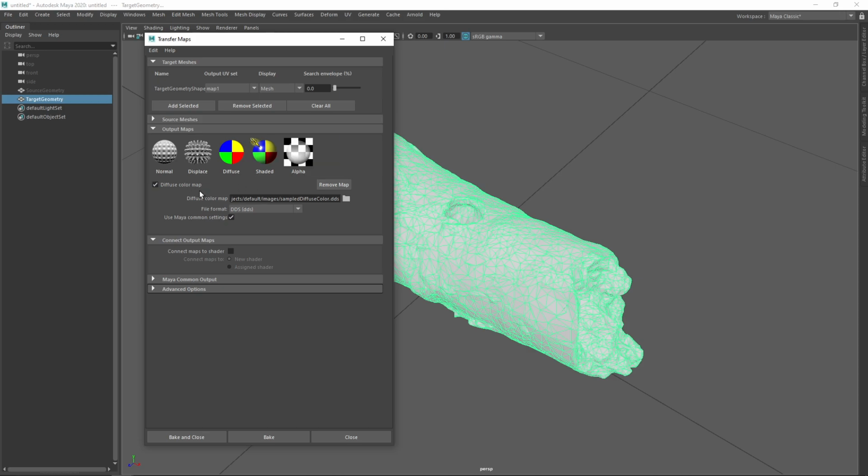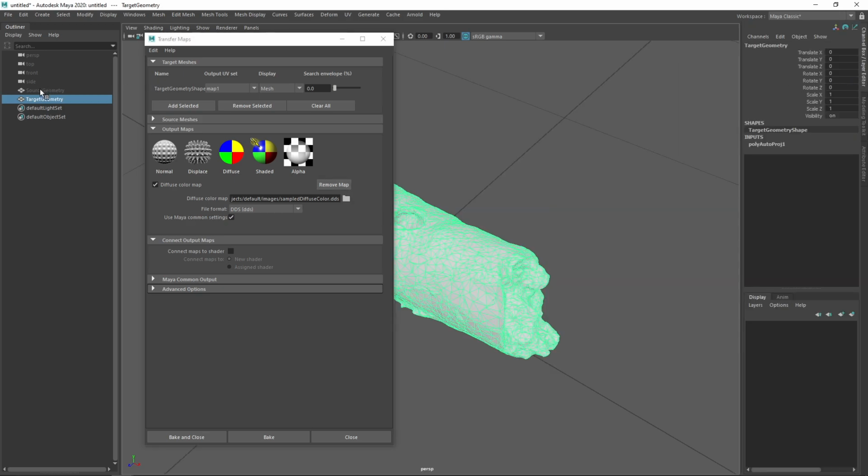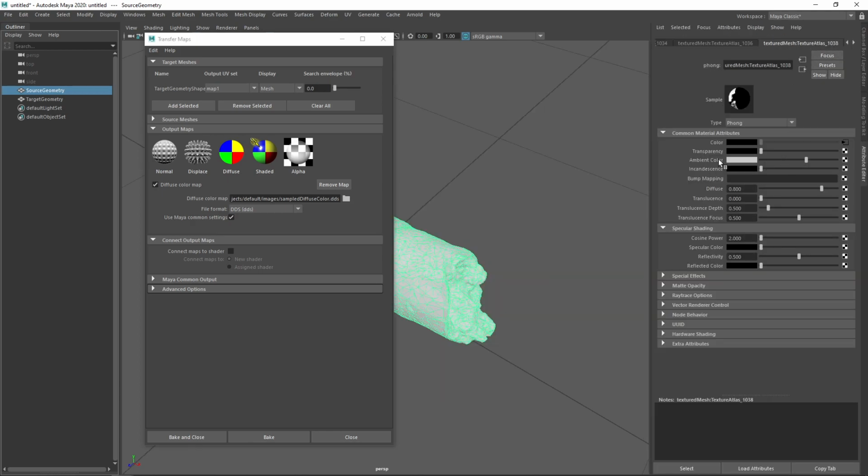And yeah, we'll have to do a bit of setup here in just a second, but actually, you know what? Let's do this the wrong way first, because there's another setting here. There is something to do with how the Phong shaders are set up with this ambient color attribute. I actually want to show the problem that the ambient color attribute causes. First, I want to show the problem so that in case you run into this problem or forget this step when you're doing your diffuse bakes, you know what to solve.